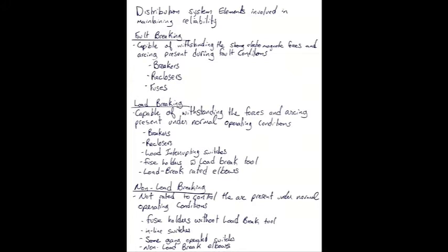So maybe 300 or 600, or if you've got a big one, maybe they've got 800 amps worth of load breaking capability. Right, so like a fuse holder with a load bust tool might be 200 amps worth of load breaking capability, whereas a very fancy automated piece of switchgear might be up to 800 amps of load breaking capability. So, in terms of your switching and doing your maintenance and working your restoration, these tools are great, but they aren't going to help you extinguish an arc under fault conditions.